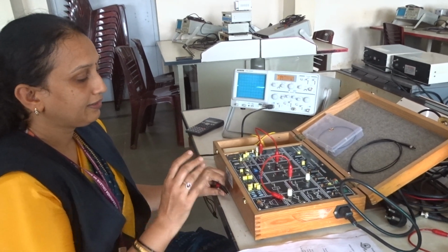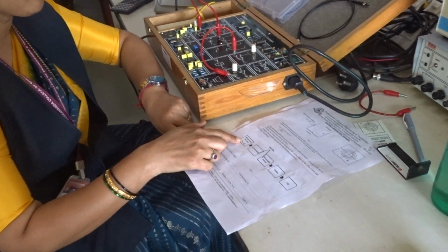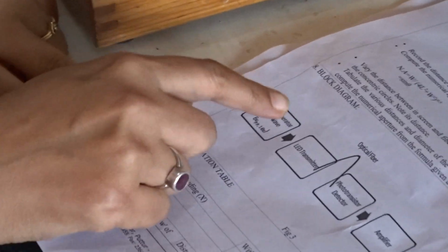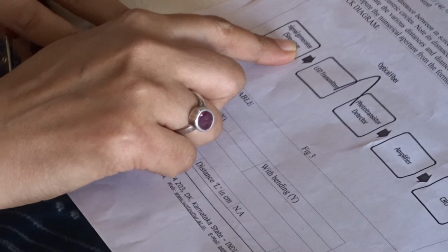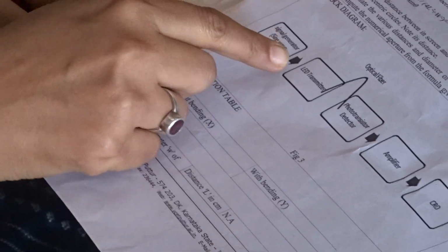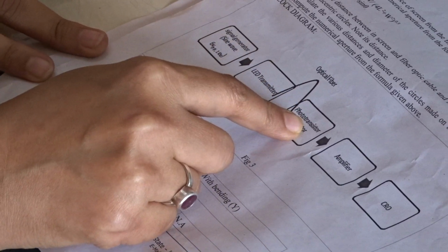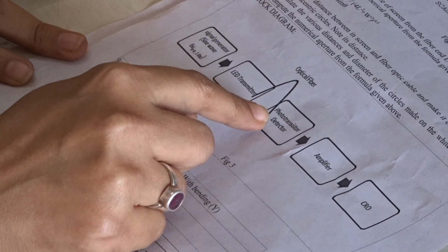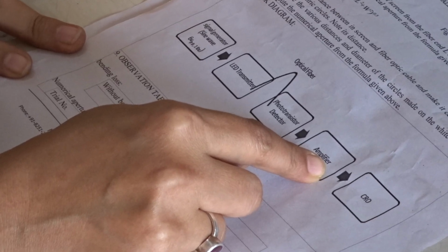In this block diagram we can see the input signal, the information signal in the form of a sine wave, will be transmitted through the optical cable by converting electrical energy, in the form of analog or digital, into an optical signal. At the receiver end this will be converted back into an electrical signal by using a phototransistor, and it will be transmitted to the receiver end.